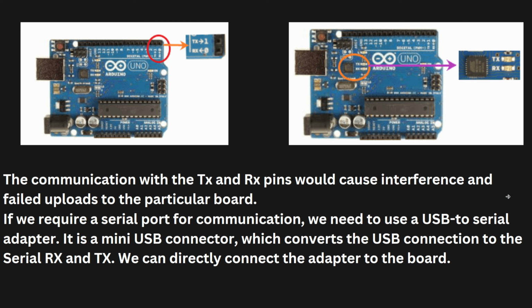So this will make the communication with the board a bit easier than what we have now with the RX and TX. If we take the ESP8266 actual board, which was launched and based on which the NodeMCU and Wemos D1 Mini have been launched, that board had RX and TX communication directly. So there you have to send the AT commands to write a logic for that board. So in future, if possible, I'll surely show that board to you guys, and I'll show how the AT commands were used to program that board.